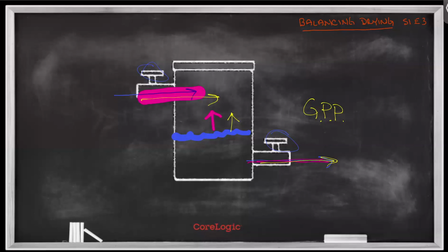So this is an important observation, but the reason I drive this really simple analogy isn't just to drive home the obviousness of what we just discussed in the previous slide. It's to start analyzing these levers. So this is something we fall short on in humidity control. The automatic assumption that most of us make when we see this happening and the humidity is increasing within the environment is that, well, I have one dehumidifier installed, that must not be enough. So let's add another dehumidifier. That's the automatic reaction. And most of the time, that's not the right answer.